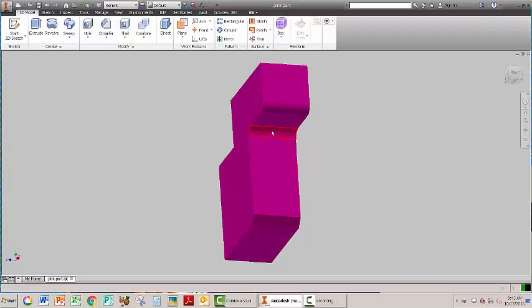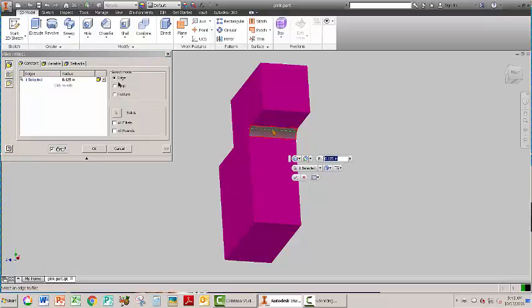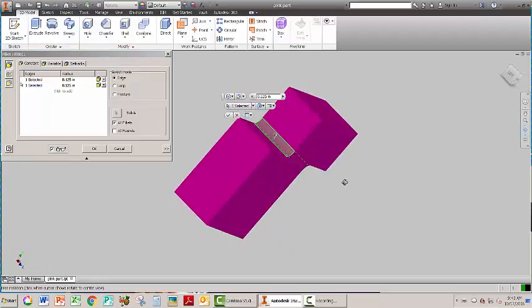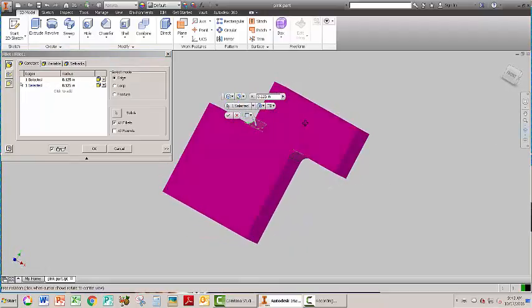Now, if I want to, I can apply this fillet, round, or chamfer across the entire surface of this part. Let's go back up into my first fillet here, and notice in my control screen one of the options is all fillets and all rounds. Let's take a look at what happens when I click each of these. Let's do all fillets first. There are only two interior edges on this part, one right here in the front and another one here in the back. If I select that, it's only going to fillet the two edges it's appropriate to.